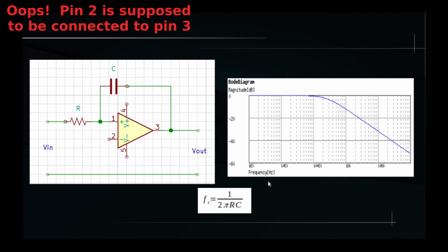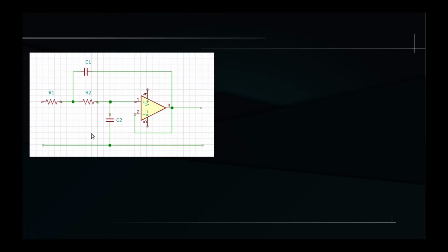The next step is now to put together 2 low-pass filters to obtain a second-order low-pass filter. You can see it in this picture and see how R1 and C1, along with the op-amp, have the same configuration as the first-order active filter we have seen in the previous picture. Now, however, we have an extra passive low-pass filter made of R2 and C2, connected just before the non-inverting input of the op-amp, and this provides a second level of attenuation of the signal.